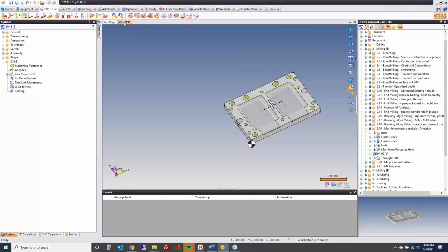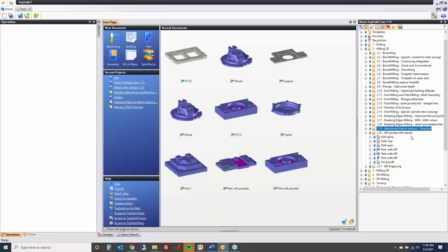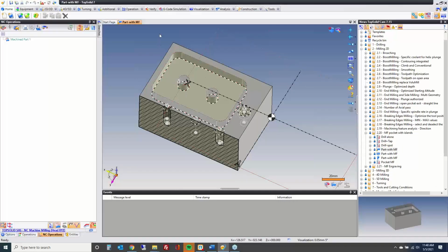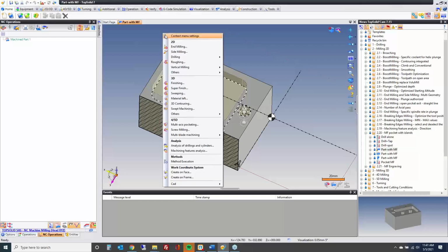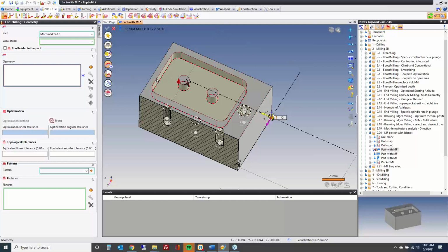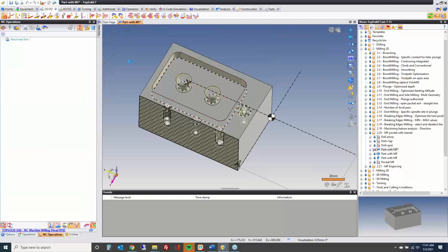All right, next one. Again, this one is having to do with manufacturing features, or as French has so lovingly called them, MFs. So, MFs. So manufacturing features, a couple of things. We've improved the manufacturing features to work with end milling and side milling, and have those features include islands as well. So if I go to end milling, I can select, and if you, I'll leave it on, doesn't matter. I can select under geometry. You see how it's highlighting the manufacturing feature, and it's seeing the island there as well.